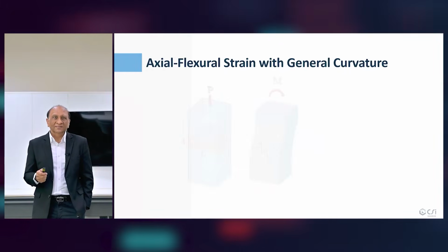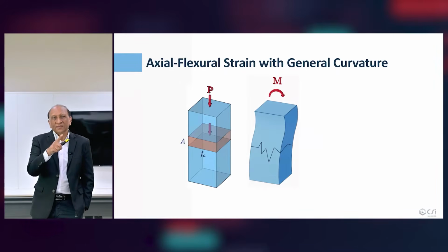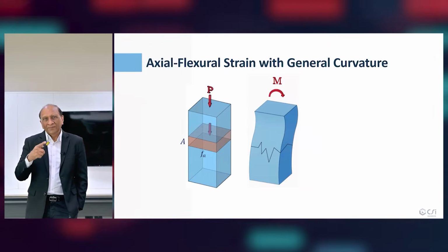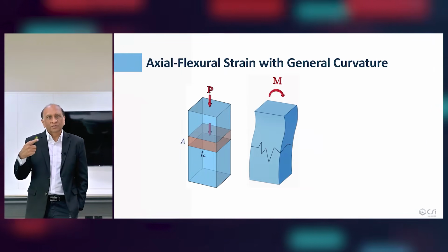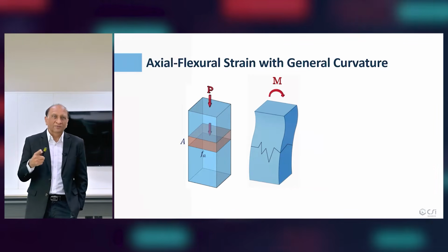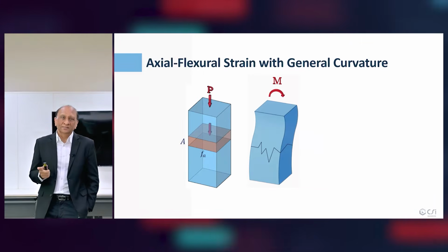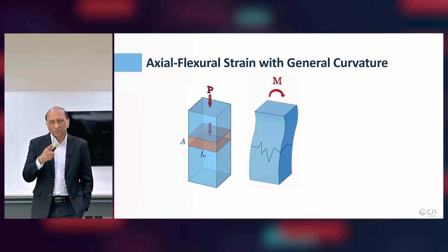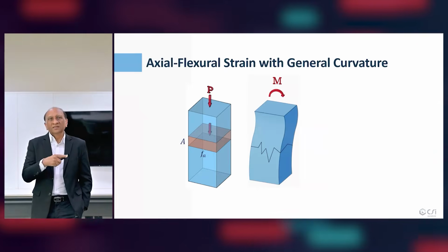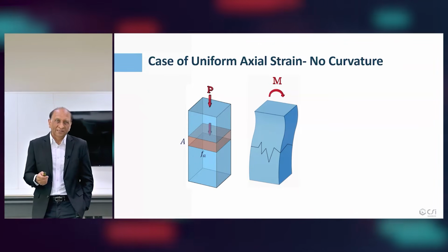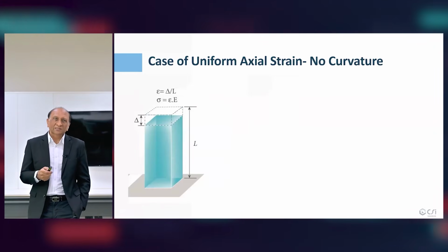So if we take that, then we can see that it is coming from two components, axial force and bending moment. Bending moment may be subdivided into moment about x and y, or moment 1, 2 and 3, whatever we call it, but ultimately it's a resultant moment that we are concerned with about a particular angle. So this combined will create a state of stress and strain that we have seen earlier. So let's start step by step.